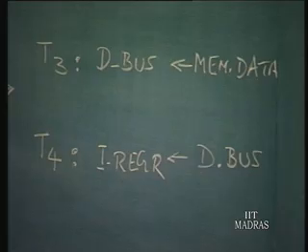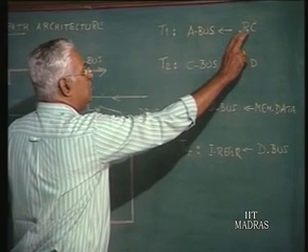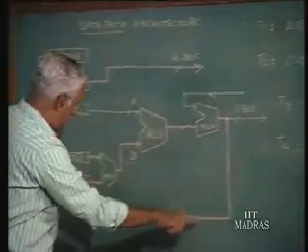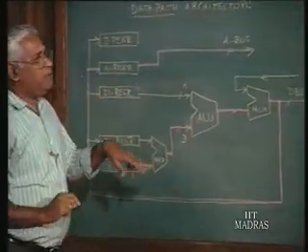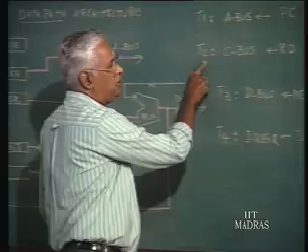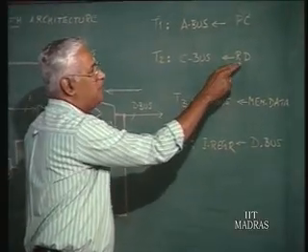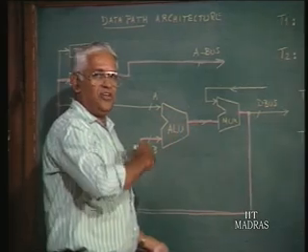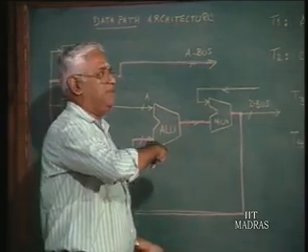Good. Here, after program counter contents are placed on the address bus, for which specifically the data path is shown, during T2 the CPU is placing the read control signal, because it has to fetch, the CPU must read in, right.